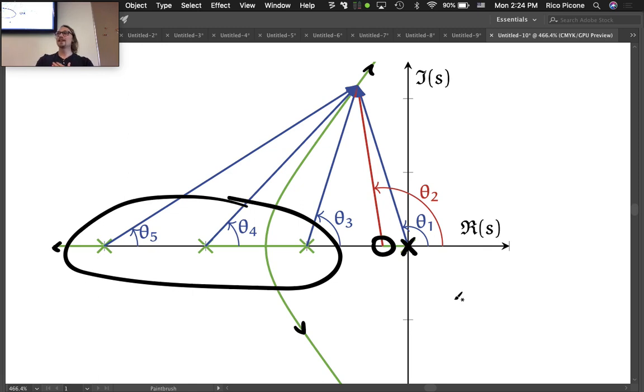So that's how we can understand why putting that 0 there is going to help us not affect the root locus too much. It will a little bit, and there's this whole sense of close. What does close mean relative to how close the root locus is going to pass to these?